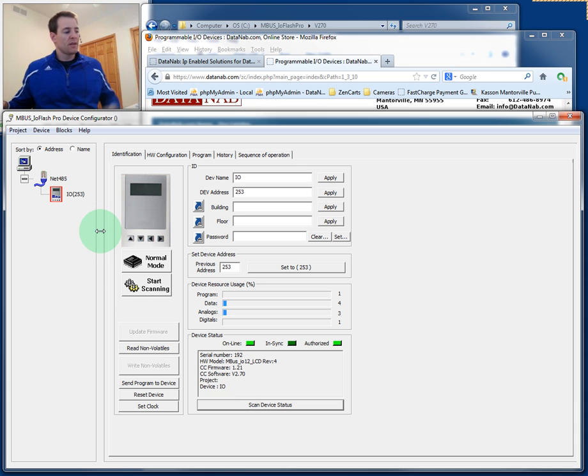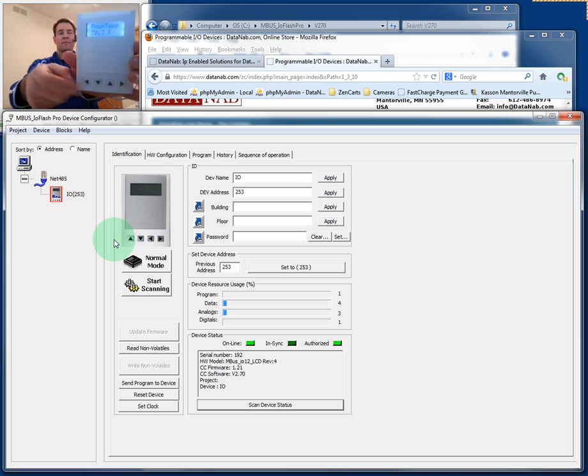Okay, so we've got our device. Let me show you what this IO12 actually looks like in real life. I've got one hooked up here. It's a really nice looking device, good plastics, a nice LCD display, and 4 buttons on the bottom here. This device actually has a push button on the bottom. You can use this to trigger things in your program, and it's got a light level sensor on the top. You can't see it, but it's inside these grates. An ambient light level sensor to sense the light level, so you could use that for occupancy or things like that, or if you're controlling dimmable ballasts, you can use that sensor for that. So that's what the device looks like that we're going to be working with here. We'll have a separate video for this device when we get it up on the website, showing you the specifics of all the I/O points and how it's designed and how you hook that up specifically.